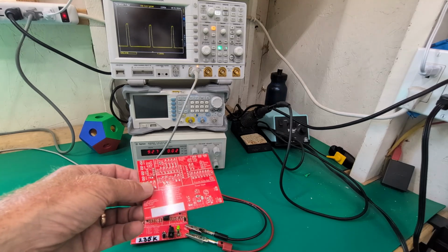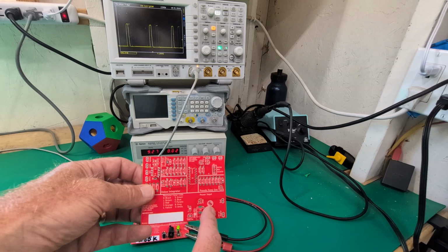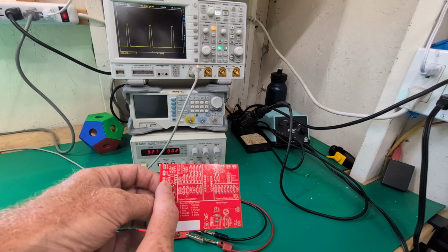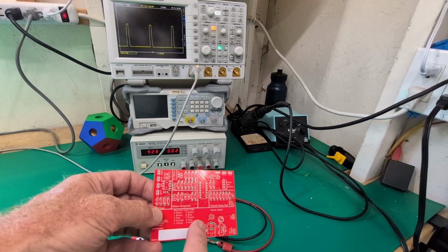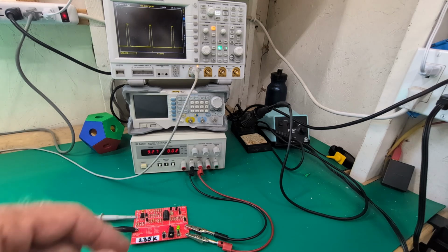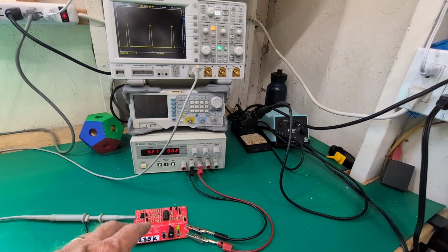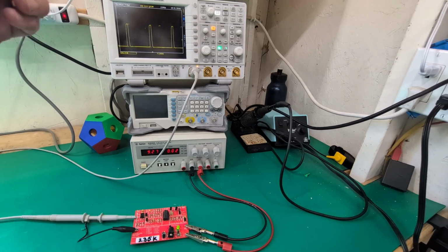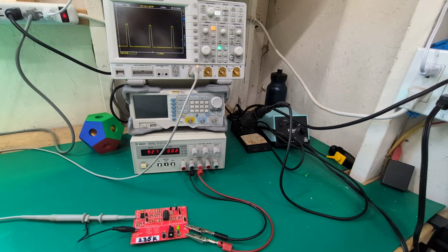In this week's lab, you'll be given an unpopulated printed circuit board and asked to assemble the power subsystem and 555 timer subsystems. These are pretty easy to identify by the white lines on the printed circuit board. The board I have shown here is completely assembled. Please do not completely assemble your board this week. When you complete this assembly, your 555 timer will generate a square wave like the one shown on the oscilloscope above. Your waveform should look pretty similar to that, but it will differ in some key attributes.